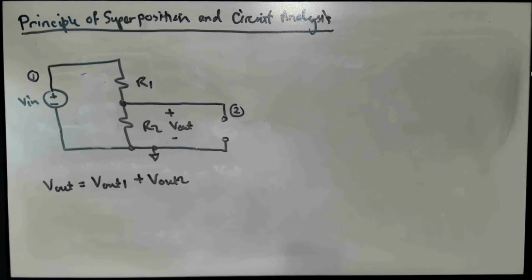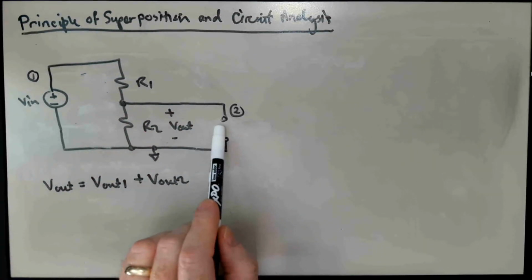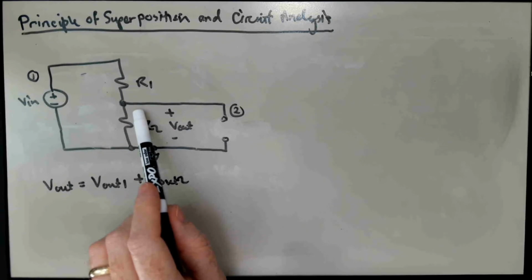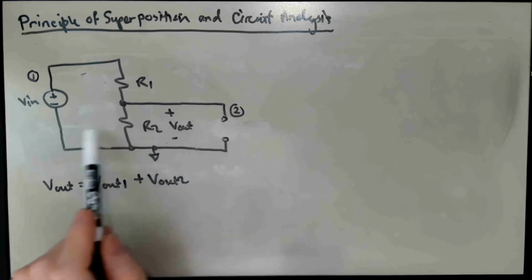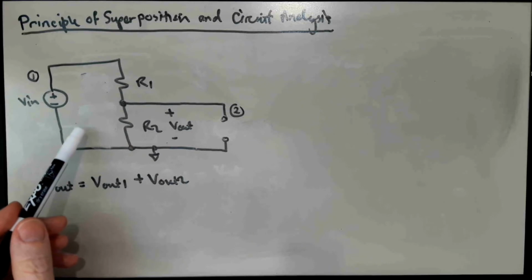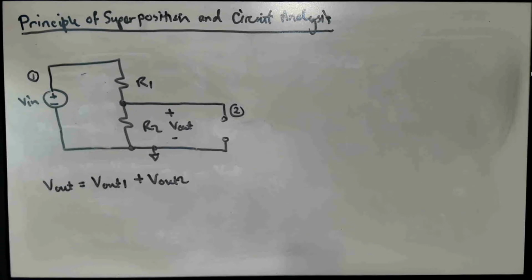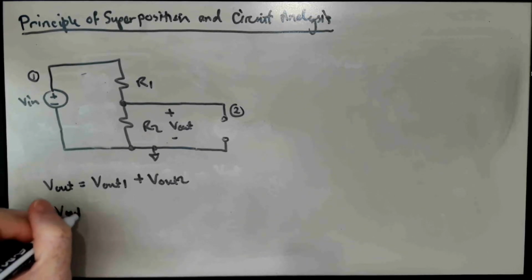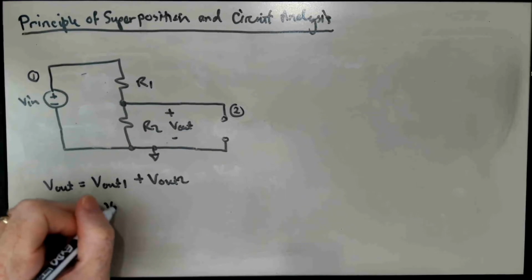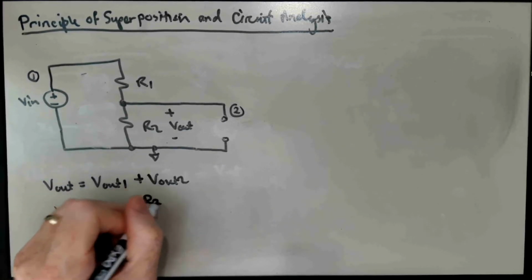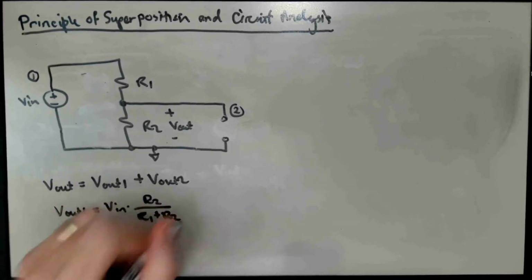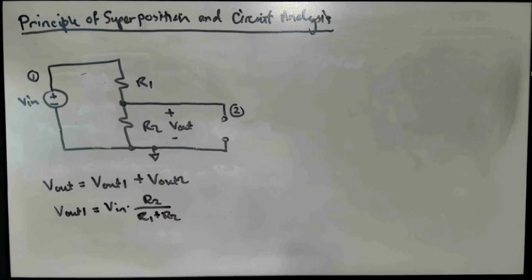Okay, now we've removed that current source from injecting a current into the output node, and we've reduced our circuit with the two sources into our familiar typical voltage divider that we've now solved. And if we put that in our L1 cache, and we can bust it out when we need it, we can write down that V out 1 is just V in times R2 over R1 plus R2. No problem. And we're done with that one.